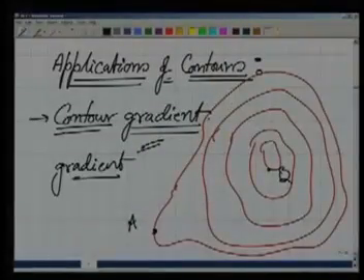That's the design consideration. So how to plan that road so that this road always follows the same gradient, number one, or does not follow a gradient more than the required one? How to ensure that? By making use of the contour map. That kind of line which follows the same gradient everywhere in climbing up the hill, we call a contour gradient. Now we will see this by an example.